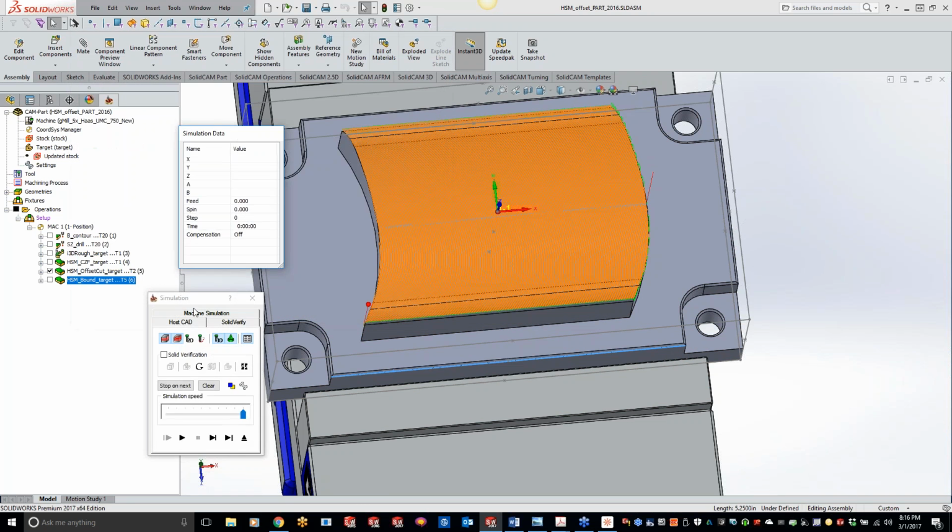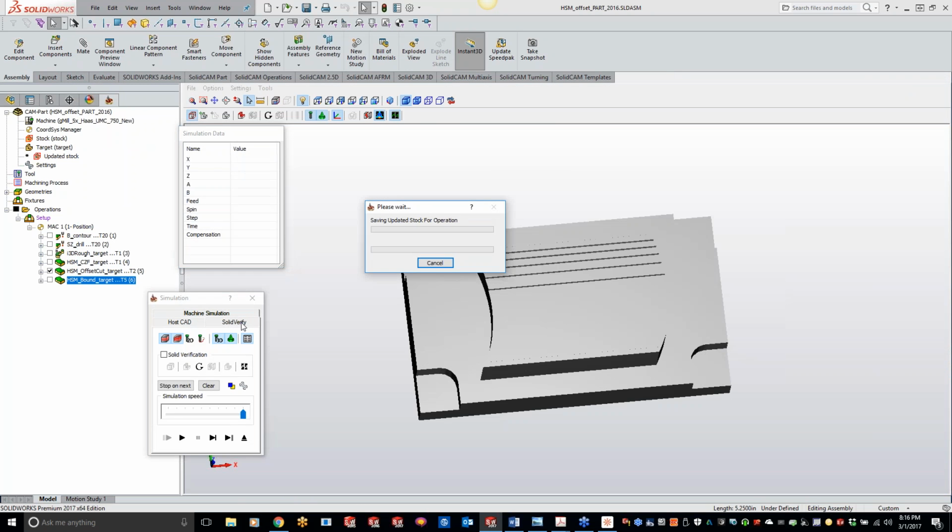Now, when we get to a part that doesn't have a chamfer on there and we're basically just looking for a nice edge break going around there, that's where you go to put your wall offset. So what we would do is put a negative floor or wall offset in there, and that would populate that chamfer for you.